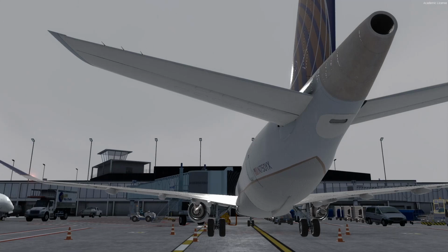The engine FADEC will take care of that minimum thrust figure, so we can put the thrust levers to idle and the engine will maintain said minimum thrust, but that minimum thrust would be slightly increased, so it may shallow our descent angle if we're trying to descend using, for example, flight level change mode, or if we're descending on VNAV path, flight path angle, or vertical speed. The airplane will meet those path requirements, but it may speed up, and if we're not too careful, it might overspeed or not meet any pre-programmed speed restrictions, for example. So we just need to be aware of those limitations.